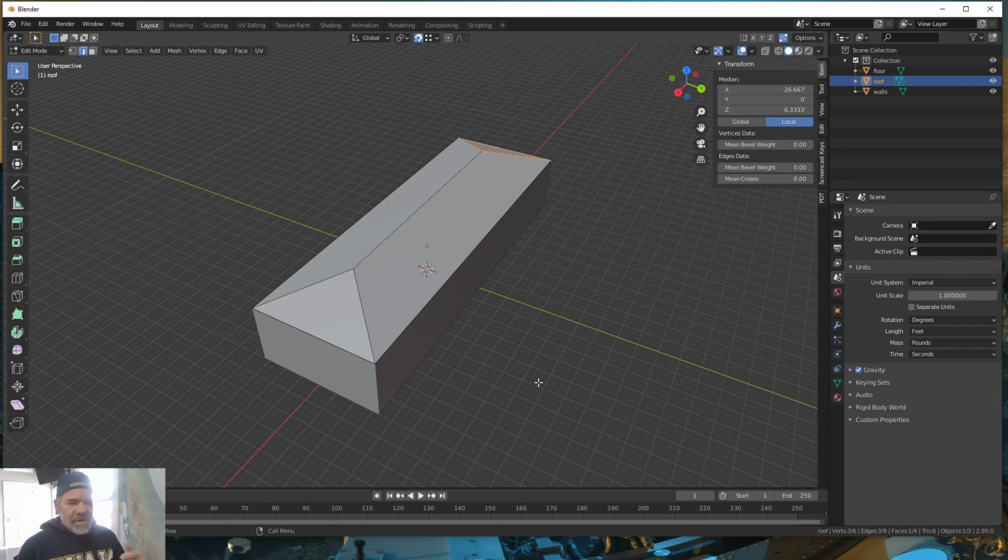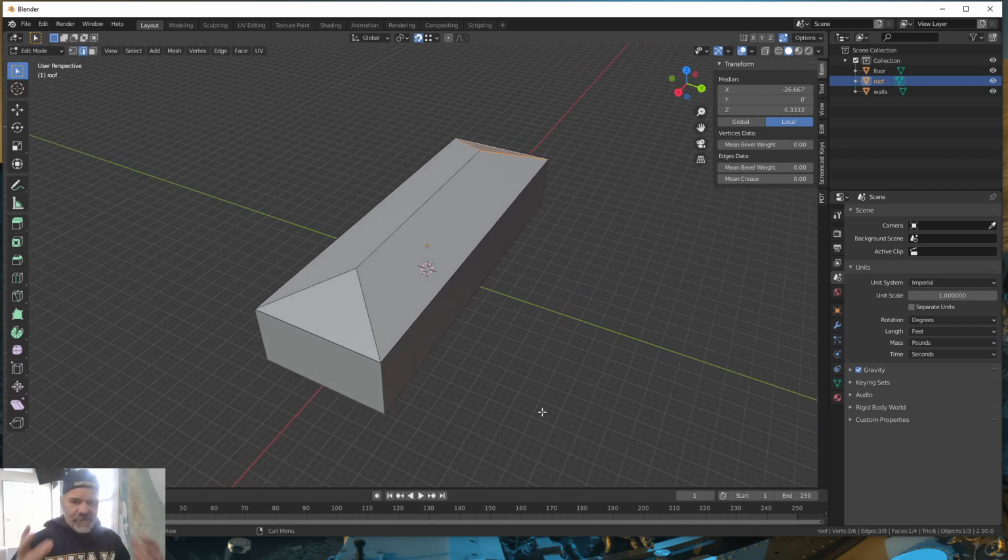What I just showed you is an extra amount of work. You can actually do this more simply by planning your polygons prior to this step. But I wanted you to see that when you have extra vertices in your polygons, the loop cut will not work. Now we're going to try that center loop cut again, now that I got rid of the extra vertices. We can go back into face and then Control R for loop cut, and now I'm able to make my cut down the middle of my building.